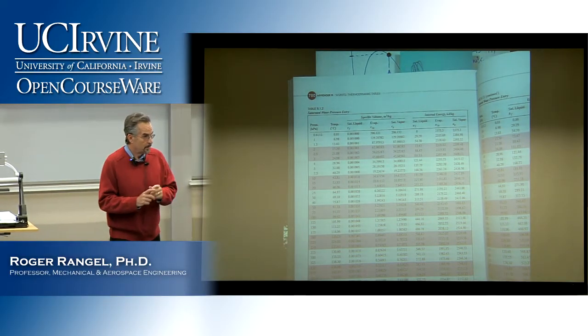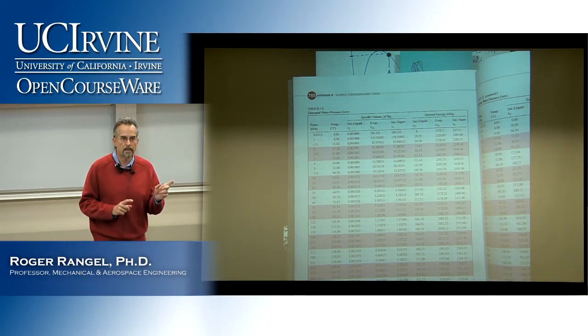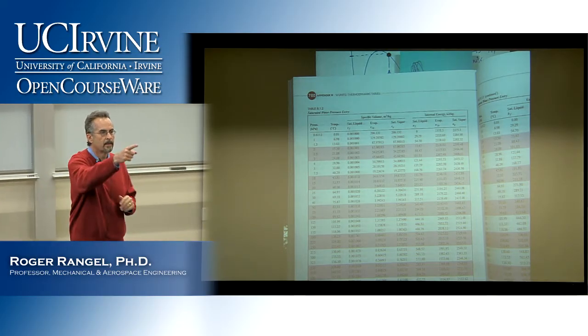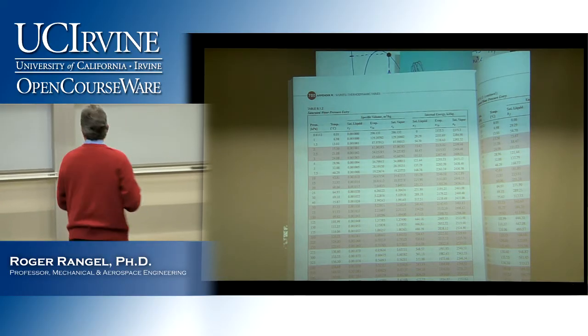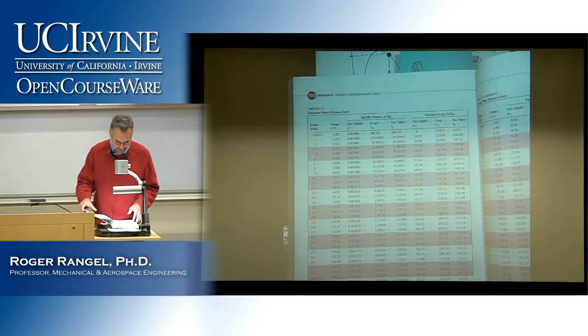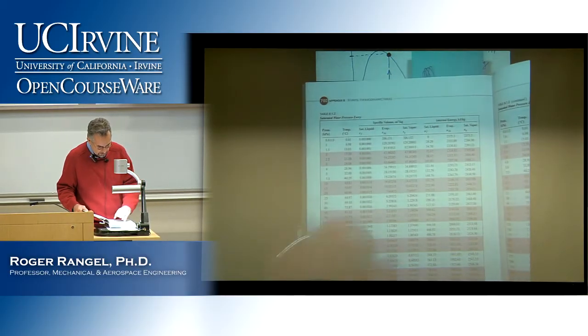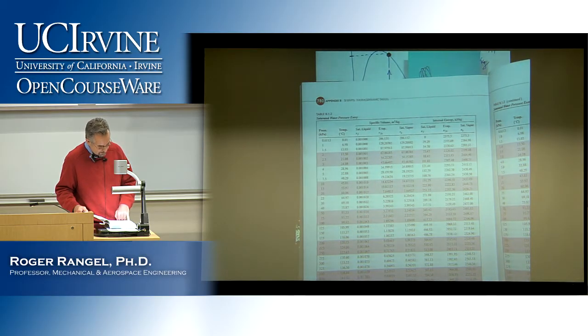Specific volume is between the fluid and the gas. Liquid and gas. No, I don't need to deal with the liquid. You're looking for a specific volume of the vapor of 0.1. Right. So I'm looking for a vg of 0.1. If I come down here, of course, this is way too low of a pressure. I go all the way down, doesn't make it.